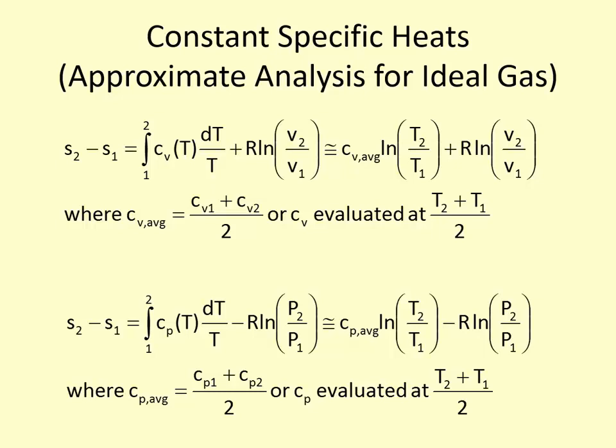So then you say, okay, if I make that assumption and I calculate this, I solve for the final temperature, now I'm left with, let's say I assume T2 was 500 and it ends up being 480. Then I can say, okay, I'm going to recalculate, find a new C sub P, and see if my final temperature value changes significantly. Or you can say, well, it's pretty close. Using C sub P at 480 versus 500 as the final temperature is so similar that it's not going to make a large difference in the final calculation. Sometimes that is an assumption that you have to make. If you don't know the final temperature, you can't calculate an average if you don't know the final, so you have to use an educated guess, and then in the end, you see if your guess was close enough.